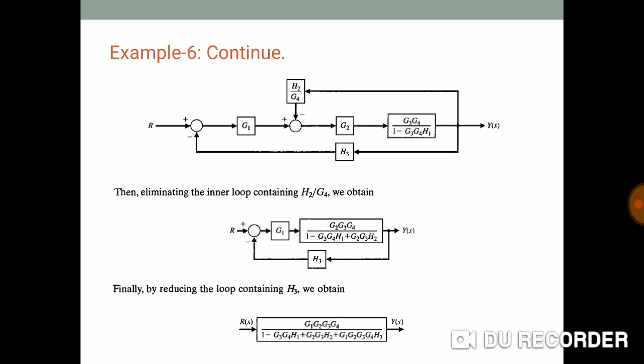Here it is, a very important formula you always have to use, that is the elimination of the feedback loop. Don't forget the formula G of s divided by 1 plus G of s into H of s, and that sign depends on what kind of feedback is there, plus or minus.